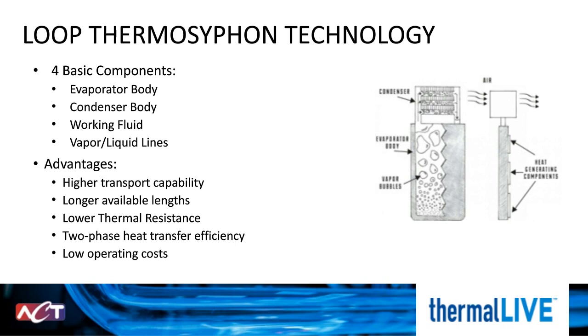Again, since this operates in a loop and utilizes both gravity and the latent heat of vaporization, we are able to handle higher heat transport capacity, go longer distances, and have a higher two-phase heat transfer efficiency. And since it is completely passive, it has 0 operating costs.